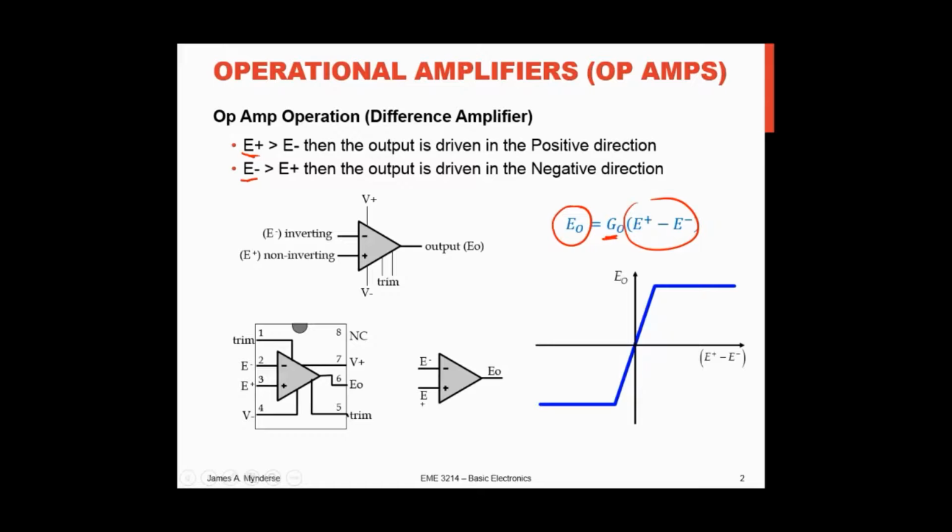Let me finish getting all of the animation. There we go. This is a practical op-amp. It has a positive voltage input, a negative voltage input, and those define the limits at which it saturates. You can't output a voltage higher or lower than the power supply that you're given, and these limits are commonly referred to as rails.